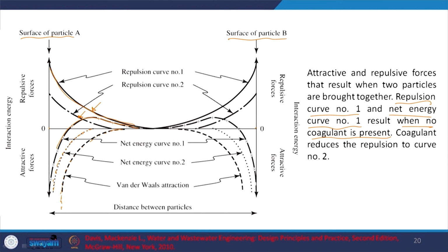By adding a charge opposite to the charge on the colloid, I can cut down the electrostatic force of repulsion. Then, as the particles come together, the van der Waals force of attraction takes over and the particles can coalesce. This process is called coagulation. I am trying to destabilize the colloids by adding a coagulant, and trigger that initial coalescence of the particles.